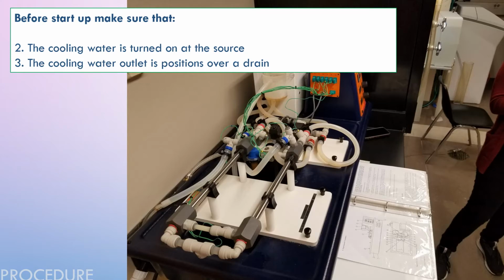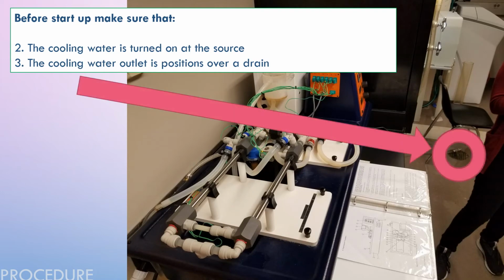Once we've determined that the reservoir has been properly filled, we turn the cooling water on at its source and position the cooling water outlet over a drain. You can see that this drain is on the lab floor, so we position a chair over it to ensure that we don't create any additional hazards while we run the experiment.